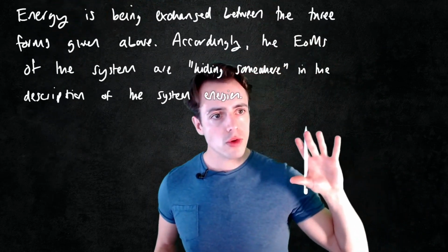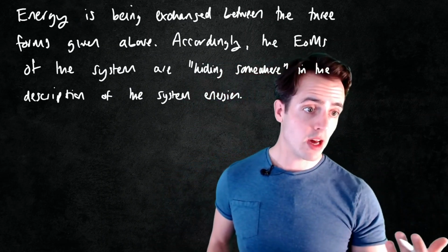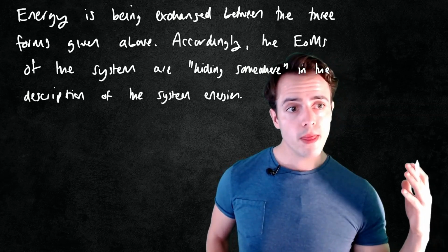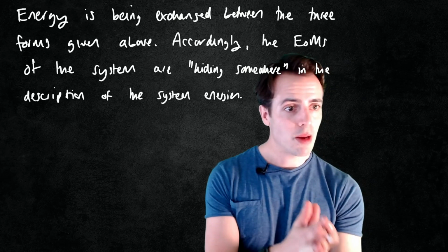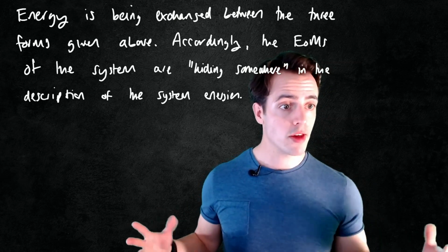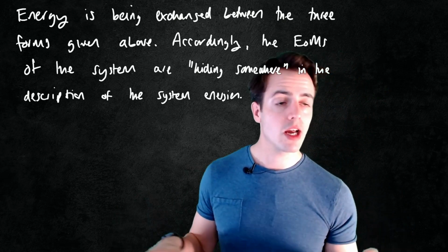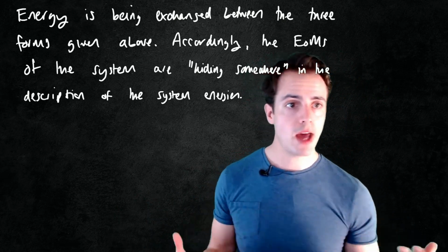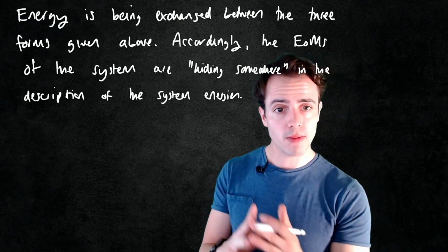So we're going to rely upon a set of equations and techniques developed by Lagrange. Now Lagrange, very famous and talented mathematician, developed a general formulation for the equations of motion of any system. We're going to use that exact formulation, and then go through this example for a panel flutter model, and we'll find that we can relatively easily develop the equations of motion.